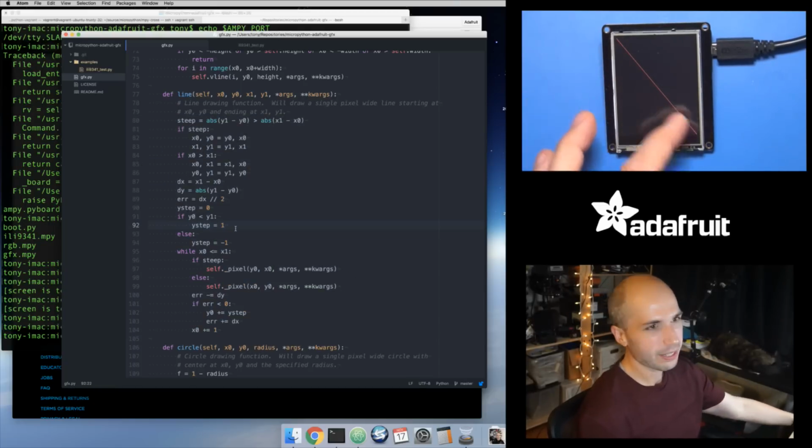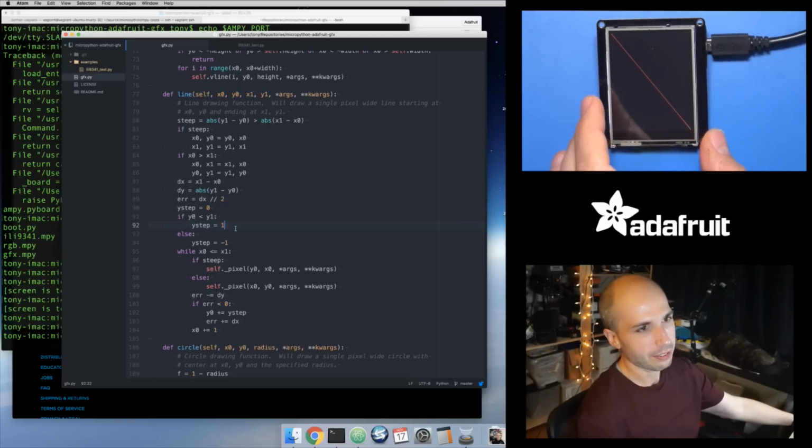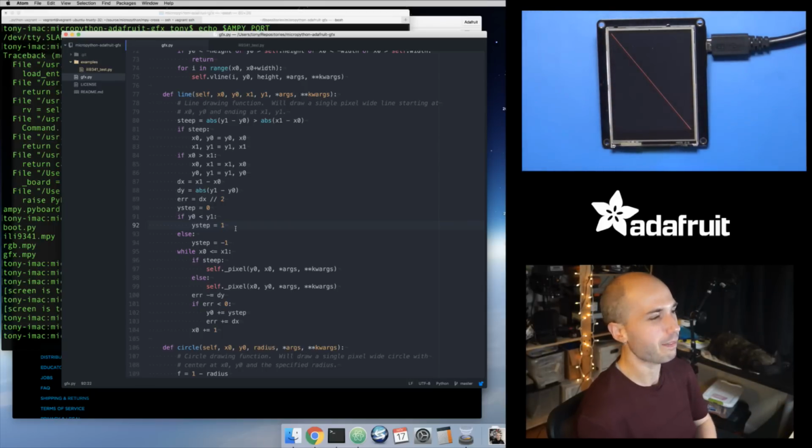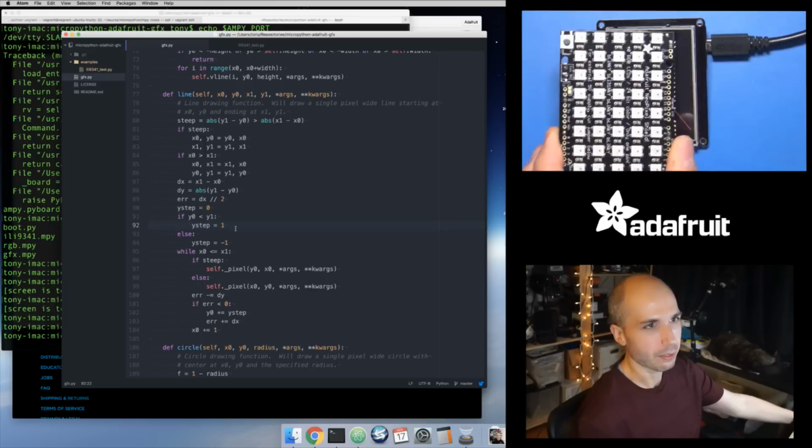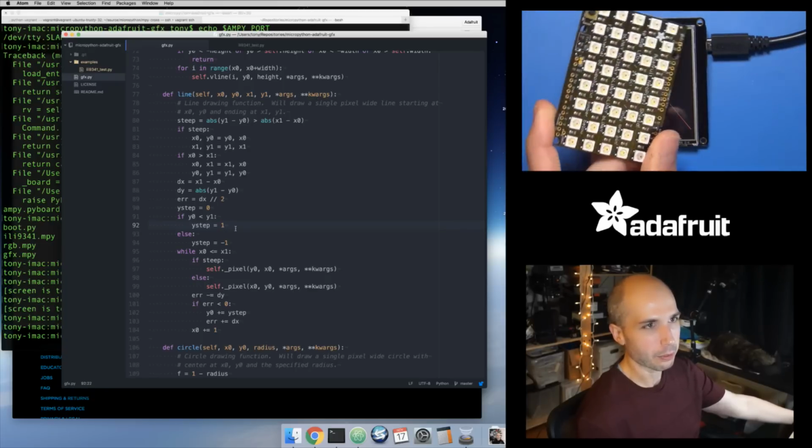So that's why you see that update. I mean, some of that is just the speed of pushing pixels over the SPI bus, but again, we're running at 32 megahertz, and so pushing a single pixel at 32 megahertz, that should be pretty fast. But calculating all those positions doesn't happen for free. So this is maybe a case where, if you're doing simple updates, like if I was writing a line on this little 5x8 NeoPixel grid,